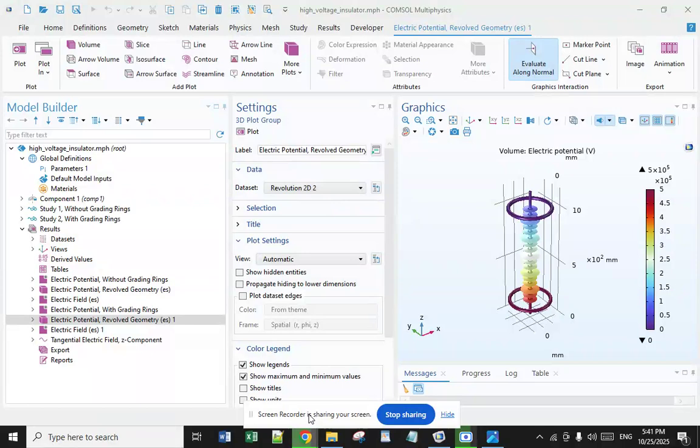Some of the most common types include porcelain or ceramic insulators. Porcelain or ceramic insulators are a common type of low voltage insulators. These insulators consist of a porcelain body attached to a metal base. The advantage of porcelain insulators is their high dielectric rigidity and resistance to corrosion, sun, and wind effects. However, they are more fragile than glass insulators and can break easily.